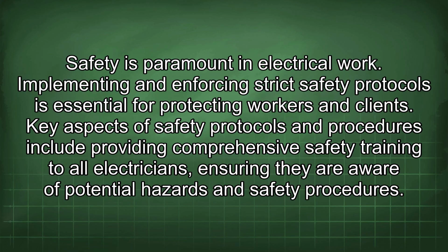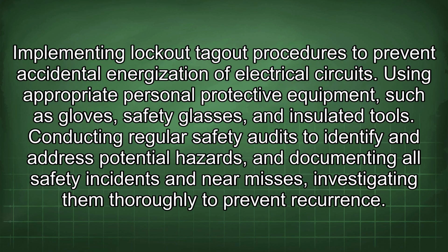Key aspects of safety protocols and procedures include providing comprehensive safety training to all electricians, ensuring they are aware of potential hazards and safety procedures. Implementing lockout-tagout procedures to prevent accidental energization of electrical circuits. Using appropriate personal protective equipment, such as gloves, safety glasses, and insulated tools.